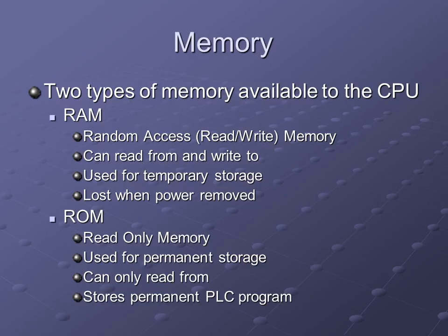And what you do is you take it and put it in this device right here, which is an ultraviolet eraser, and it will erase it. And then I have a programmer somewhere around here, and in this program right here, you then reprogram it.